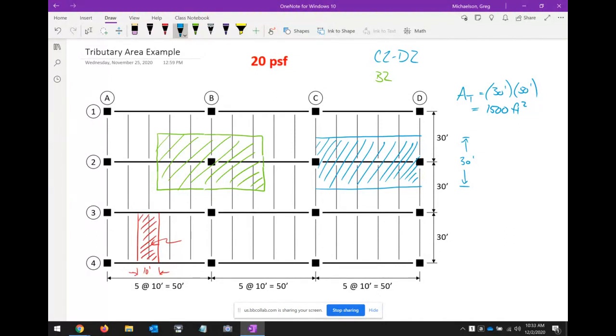The two things you have to watch out for are, one, are you accounting for the entire floor area? In other words, when you do the load takedown, make sure the sum of forces in equals the sum of forces out. The second issue is, when possible, you'd like to repeat structural elements as much as possible. For example, what is really different between this floor beam and that floor beam?